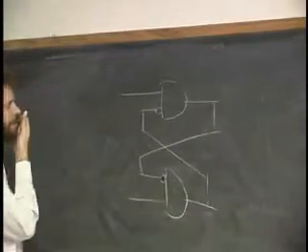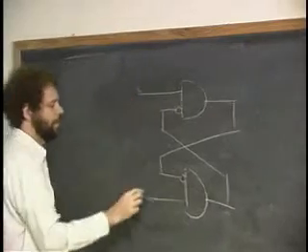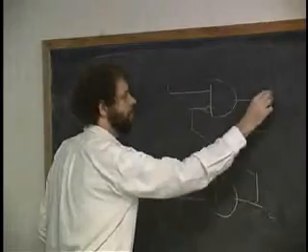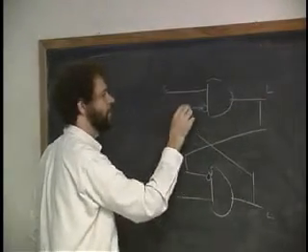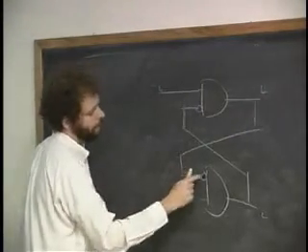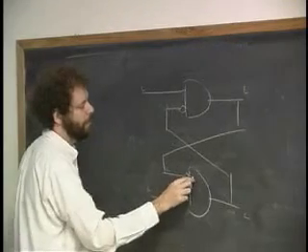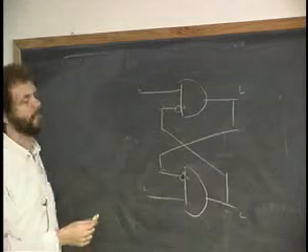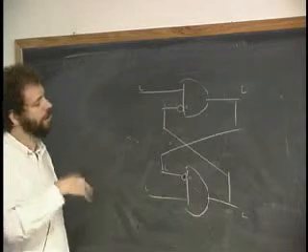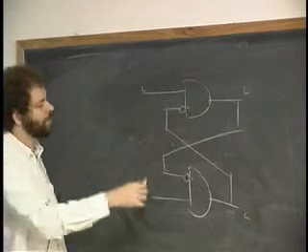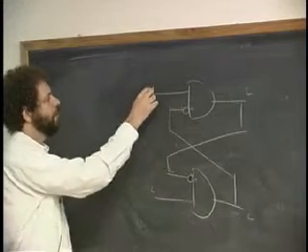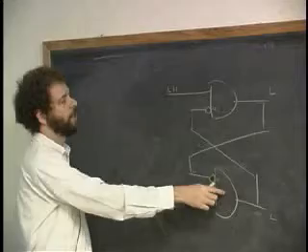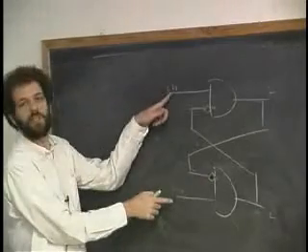Okay, so we said we're going to start out with both of these things being low. Low, and the output from here we said was going to be low. This was going to be low, and this was going to be low over here. And this gets inverted on the inside to become high. Now both of them are going to go high at the same time. And just taking an extremely crude model of time, where time just goes in steps with the letters on the board, let's say they both go high at the same time. What's the output of both of these AND gates if both of these go high at the same time?